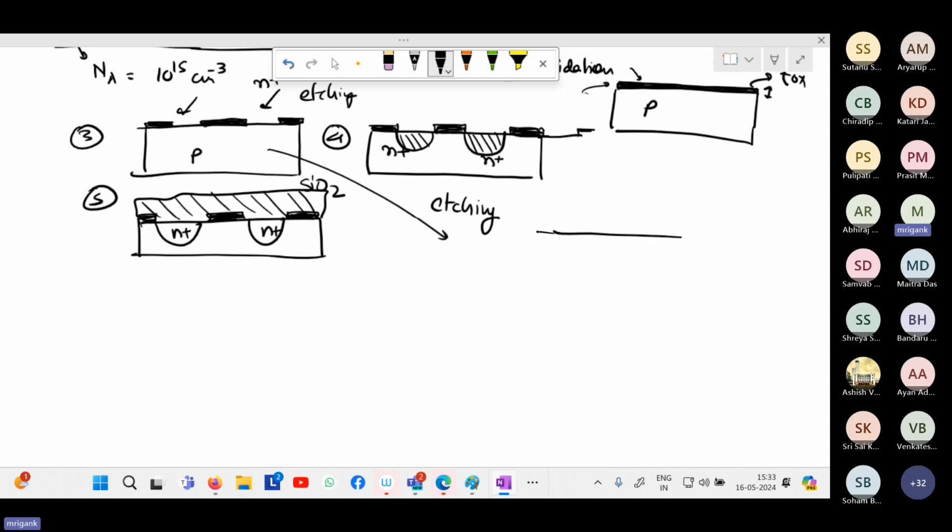So this is the oxidized wafer you started with. It has that oxidized layer, thin TOX, and then I need to open some pockets by etching. For that etching, we need to deposit a mask on it. So there is a mask using some special polymers. Masks are created, like these are masks. This is a mask using some polymer, which is going to be resistant towards chemical etching.